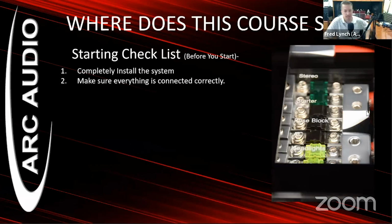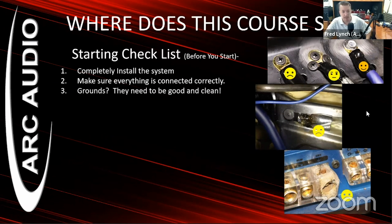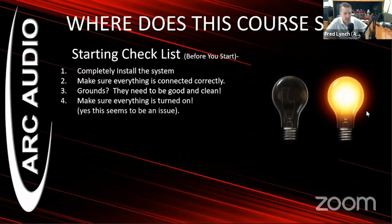Make sure everything is connected properly. Fusing, polarity on wiring, your RCAs, make sure you have signal passing through everything. These are some of the more important things that, honestly, if you don't make sure this is taken care of, you're going to have an uphill battle the whole way. Grounds, they need to be good and clean. You need to make sure that you don't have noise in the system. These are all things that are going to affect the performance of your system and the quality of the sound that you get for the end product.